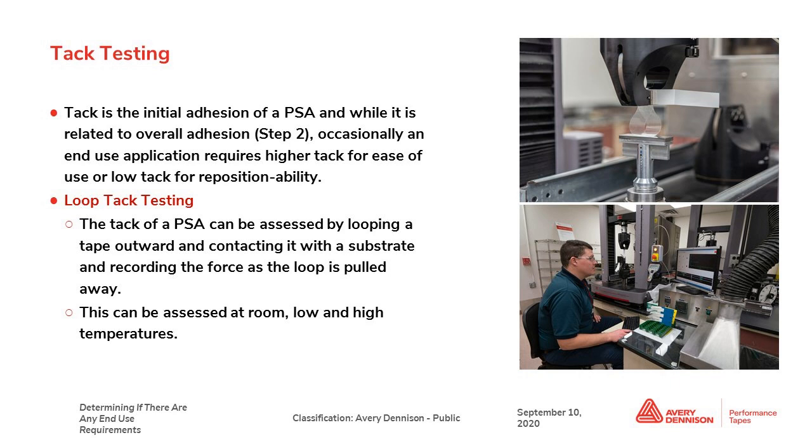Repositionability is basically just the inverse of high tack. So you want a low tack adhesive, like HPA, for example. And I will say the time window for that is always a case-by-case basis. It will depend on the substrate and the adhesive. But generally speaking, for a low tack adhesive, you have a window of a few minutes to reposition that before the adhesive really dwells and gets a high bond.